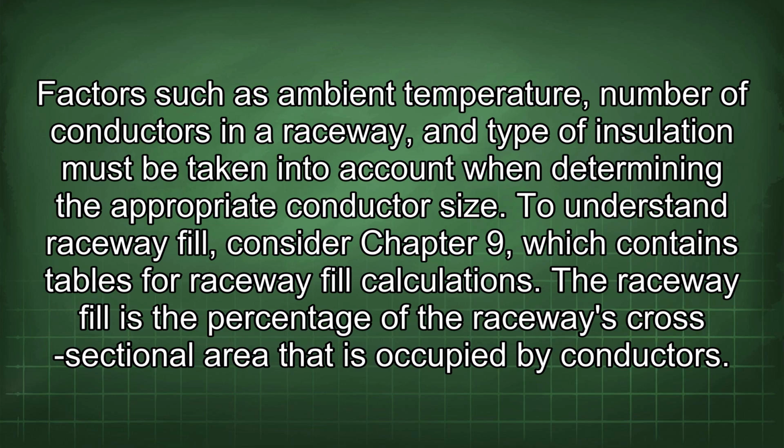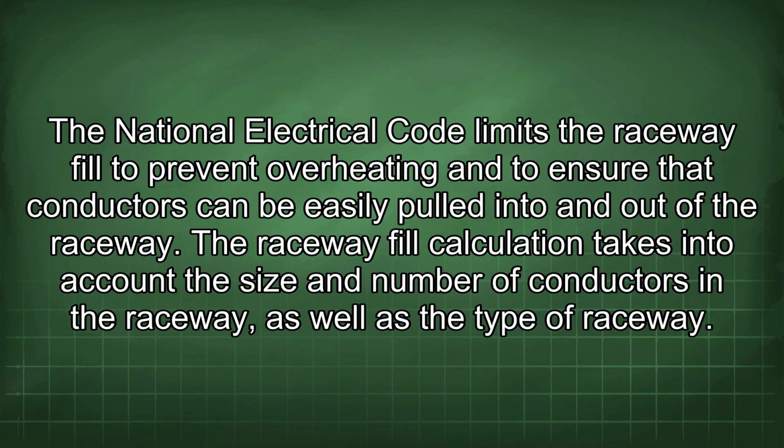To understand raceway fill, consider Chapter 9, which contains tables for raceway fill calculations. The raceway fill is the percentage of the raceway's cross-sectional area that is occupied by conductors. The National Electrical Code limits the raceway fill to prevent overheating and to ensure that conductors can be easily pulled into and out of the raceway.